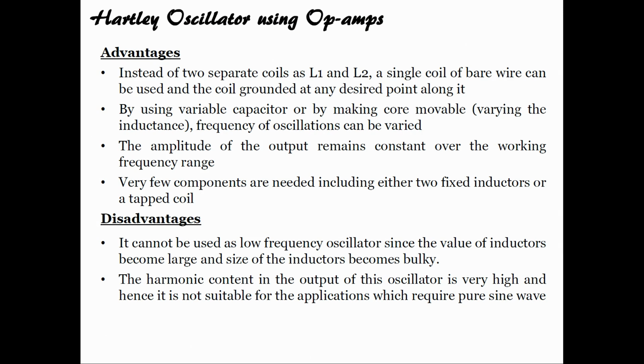But there are a few limitations. What are the limitations? It cannot be used for low frequency oscillation, since the value of inductors becomes large and the size of the inductor becomes bulky, it is obvious. The harmonic content in the output of this oscillator is very high, and hence it is not suitable for applications which require a pure sine wave. So, the harmonic oscillations limit its use for pure sine wave.